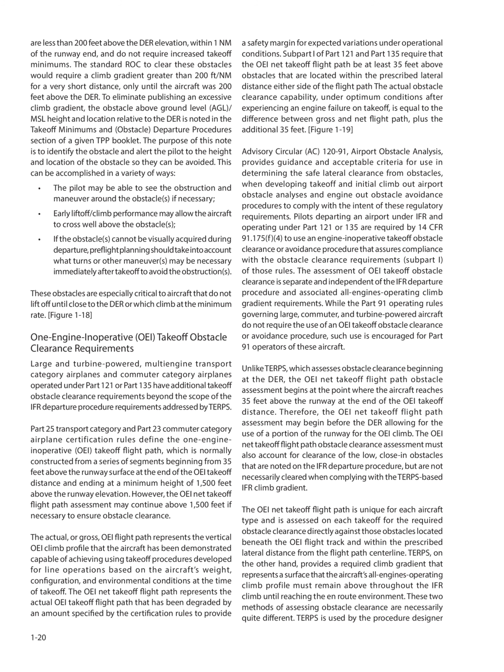This can be accomplished in a variety of ways. The pilot may be able to see the obstruction and maneuver around the obstacles if necessary. Early liftoff/climb performance may allow the aircraft to cross well above the obstacles. If the obstacles cannot be visually acquired during departure, pre-flight planning should take into account what turns or other maneuvers may be necessary immediately after takeoff to avoid the obstructions.